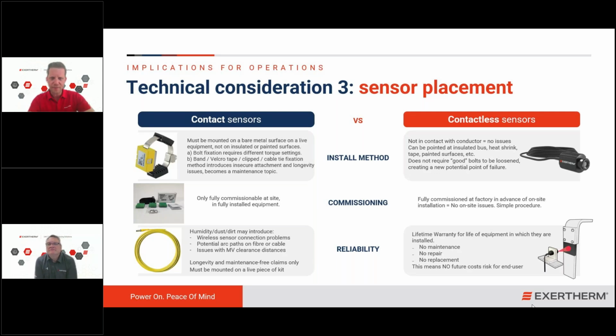On the other hand, let's take a look at contactless sensors. When sensors are not in contact with the powered conductor, there are no issues with sensors becoming loose, or becoming subject to temperature rises and drops. It can be pointed in a flexible way at insulated buses, at heat shrinks, at taped buses, or even painted surfaces, and ensure accurate temperature readings.